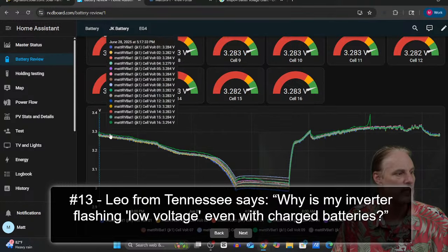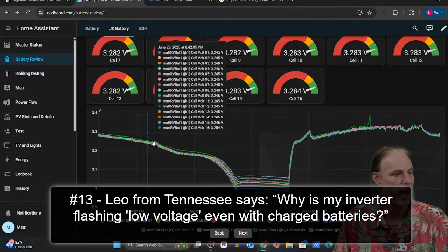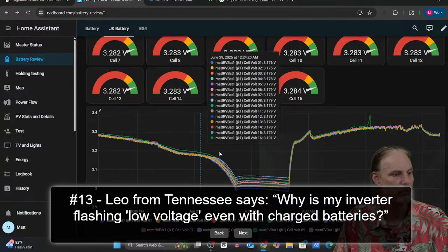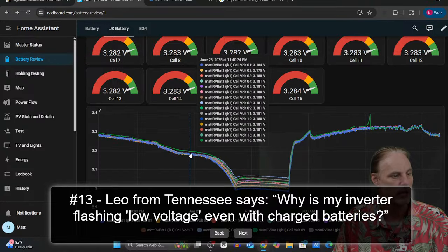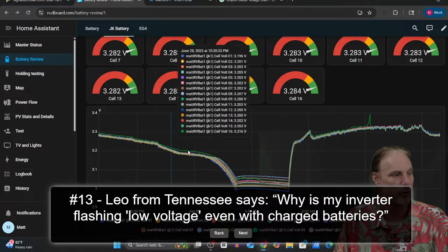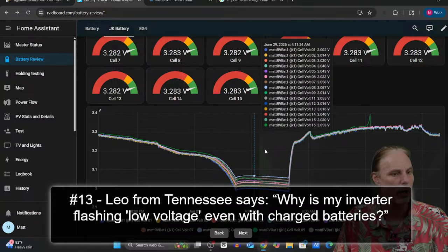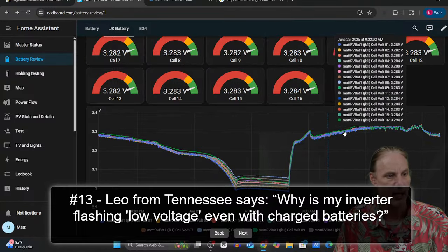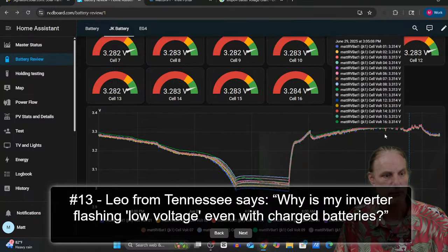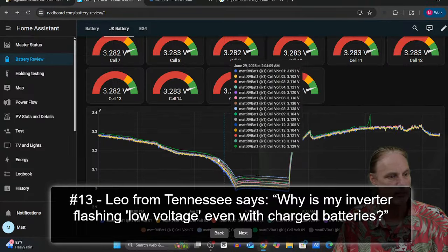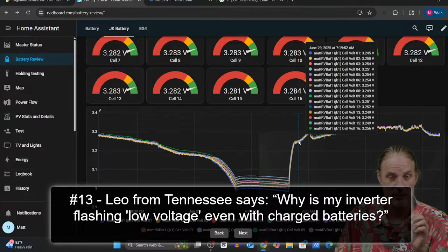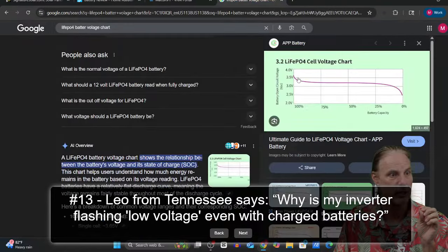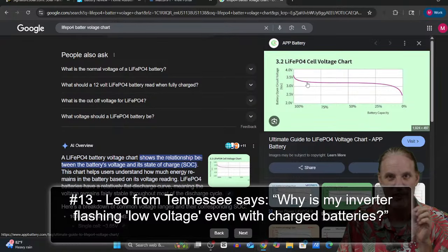So you can see that until this battery starts getting down into the state of charge at the end of the evening, it pretty well holds at 3.3, 3.4 all day as this battery is running. The only time it dips below this or above this is in that chart, where it is below the bottom 10 or 15%, or what they call the knees.